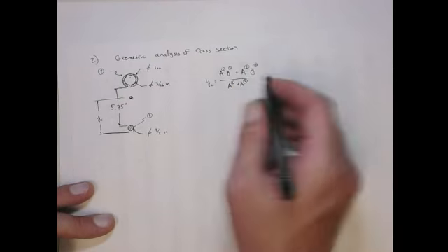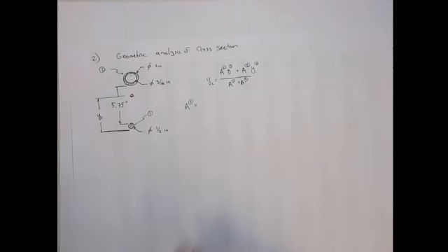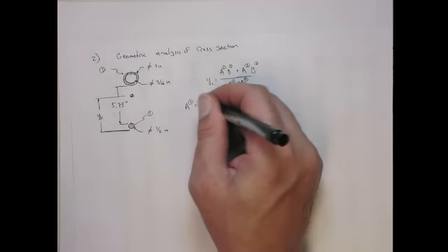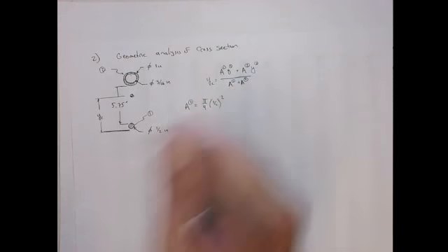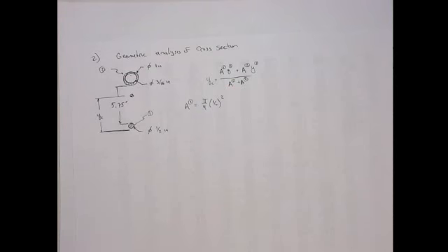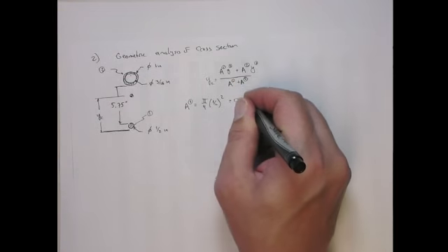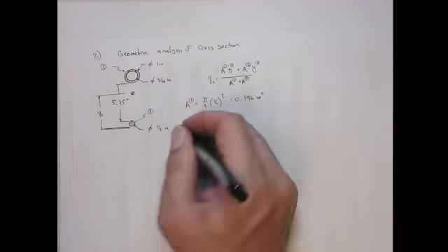All right? So let's kind of tabulate those. The area of the first one is going to be the diameter squared over 4 times pi. So it's just going to be pi on 4, 1/2 squared, right? So that's 1/4. So that's pi over 16, which is 0.196 inches squared.